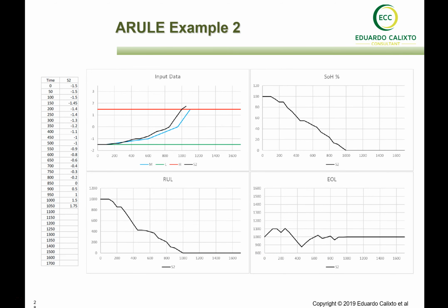But let's see example two, and that's the usual one, where the real information that comes out from the sensor does not fit 100% on your model profile that you define. So in this case, you have in the end the final prediction periods before this 1,100. So the remaining life is 100 days before what is expected. And that's very important information.